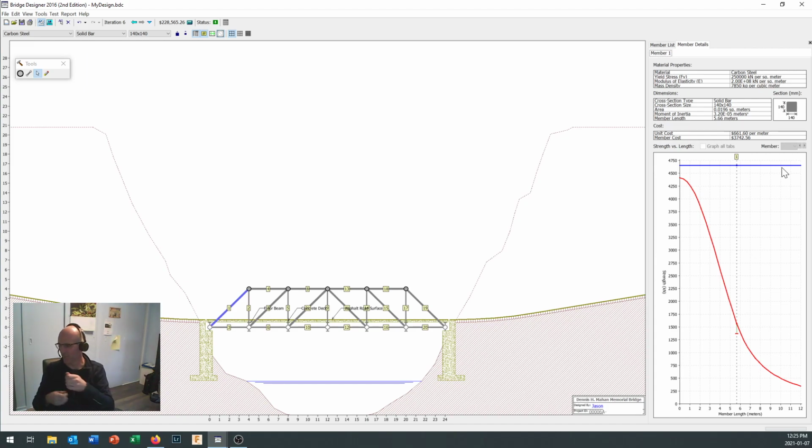And what controls how easily it buckles, bends, flops, or flips is the material that I've chosen, the length of the member, and the cross-sectional design of the member right here. So for this simple carbon steel solid bar, what you can see is that its compressive strength reaches a peak almost equal to its tensile strength when you've got a very short member. But as the member gets longer and longer and longer, it gets weaker and weaker until it's almost useless out here if you had a really long member.